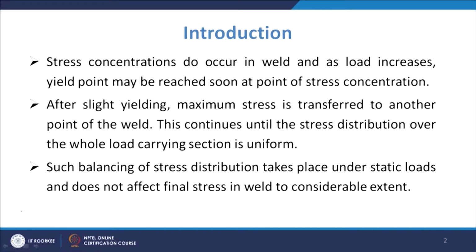When the yield point is reached, there will be small yielding, and then after slight yielding, this maximum stress will be transferred to another point of the weld. When you have some straining, at that other point where the other stress concentration is achieved, the stress value will be more than the limit. So it will be shifted to another point.